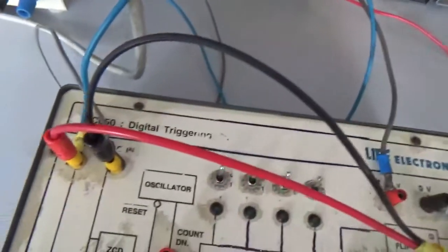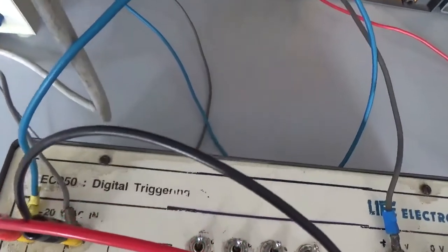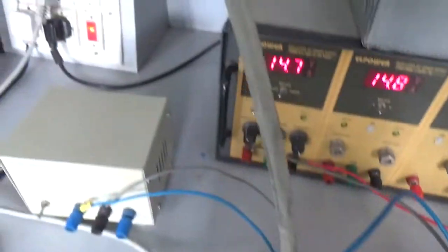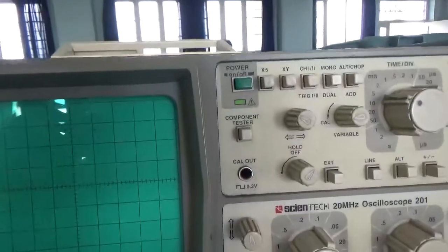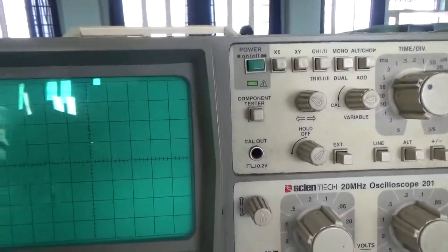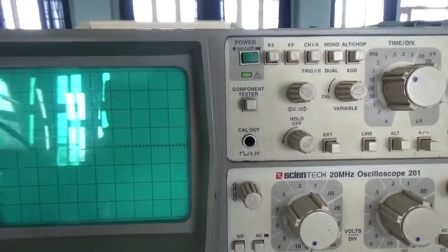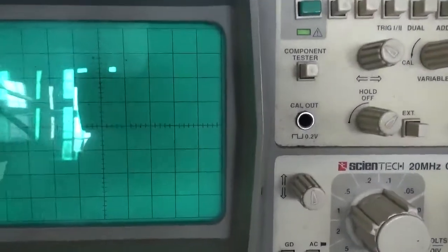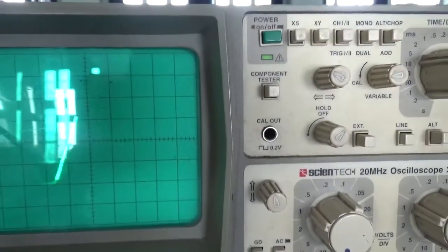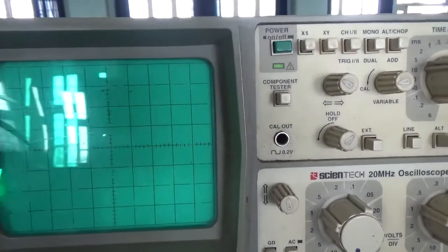But we have given 15 volt AC here. The 15 volt stands for the RMS voltage. So 15 volt from the transformer into root 2 gives 21 volt theoretically. Practically you are getting 20 volts. There is no guarantee that we are getting exactly 15 volt AC, so practically we get 20 volts AC peak value. RMS is 15 volt for this.